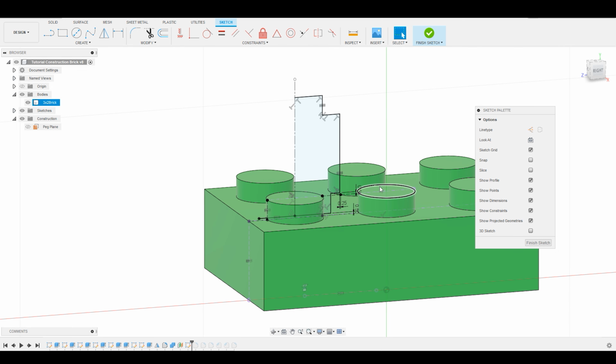But for now, this is a good example, especially as you're starting out, of understanding the thinking of how you're making sure that new geometry is referencing old geometry so that as you update things and as you change things, the model won't break down and you don't have to go back and dimension every single sketch. Look at how many sketches we've got at this point, right? Even in this very simple model, we've got a lot of sketches that we would have to go back through, figure out what we dimensioned where. So the fewer dimensions that you can have in your actual model, the better.